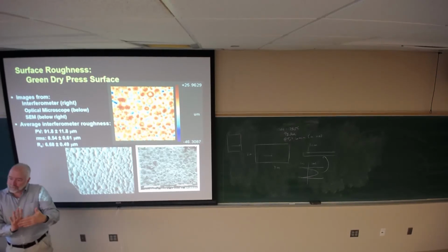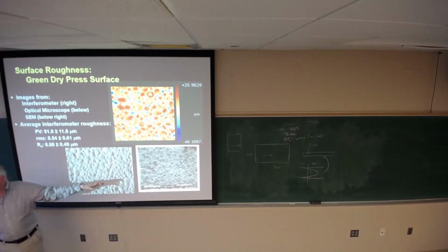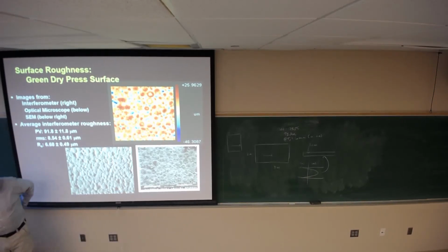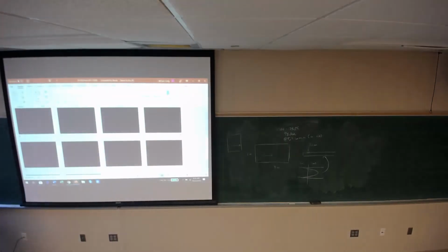And when you put in a poorly tempered piece, it bends light. You can then see it, right? So if you take tempered glass, you can see the stresses that are still in the glass. You can't do that with porcelain because it's not transparent. So how do I do it? We think we can do it by fractography. We can look at the fracture surfaces and determine there's a surface compressive layer.